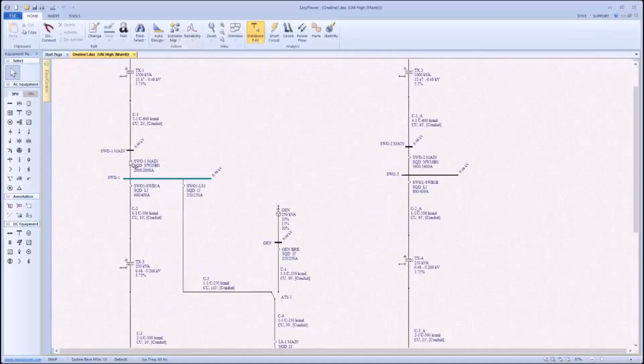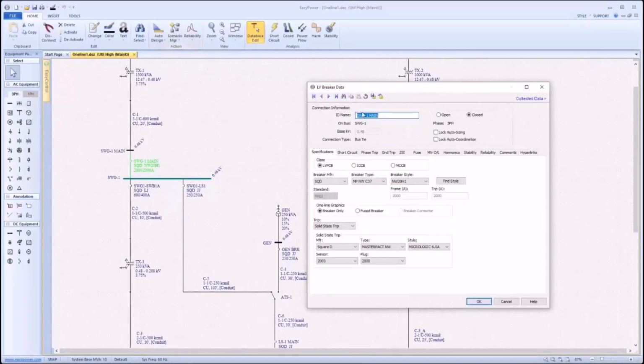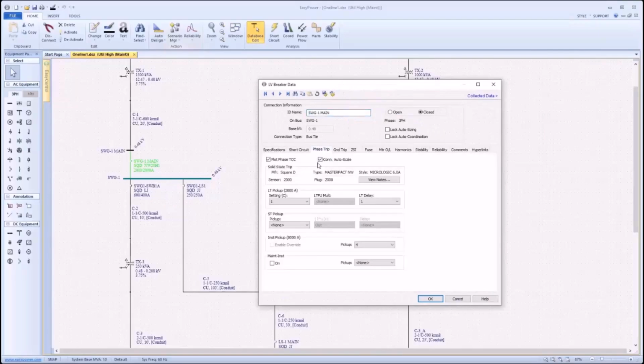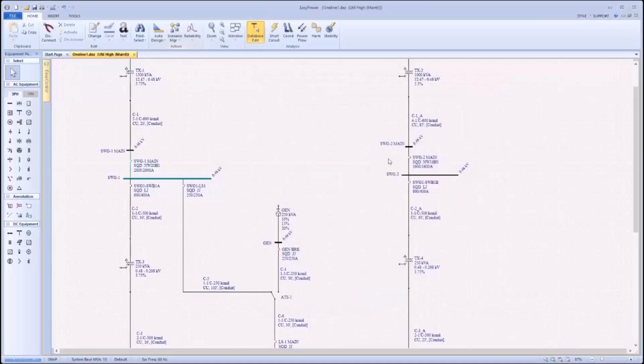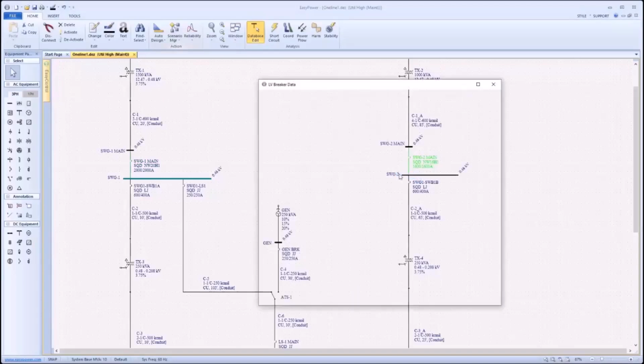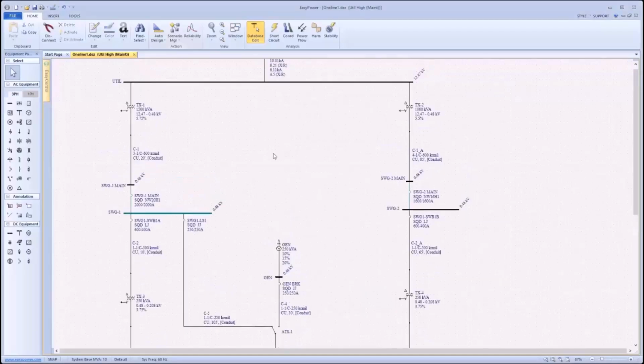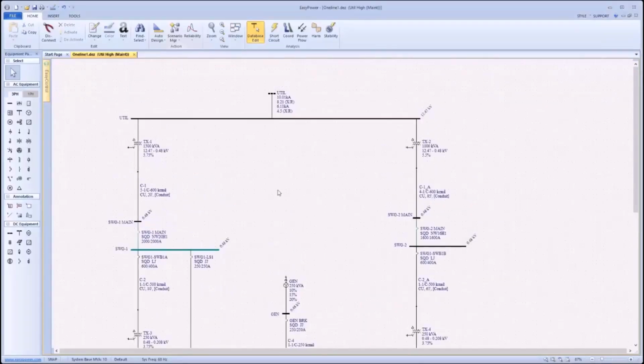And what we're going to do is I'm just going to come in here to these breakers. And you can make any settings changes. We'll see that here in just a minute when I make some recommended settings changes and TCCs. But for this case, I'm going to turn maintenance on. And we'll just go ahead and set it to minimum here. Maintenance on. You can see that gets highlighted. I'll come in here. Sorry, and I'll turn maintenance on. Minimum highlighted. So perfect. I've got both those breakers set to the maintenance settings.